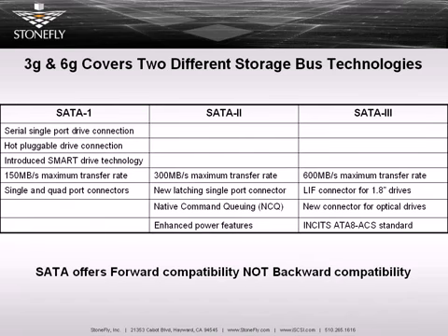SATA has grown and added features. The first thing that revolutionized everything is that it's a serial drive with a much smaller cable, 6 conductors versus over 30 for the old parallel technology. So we simplified cabling.